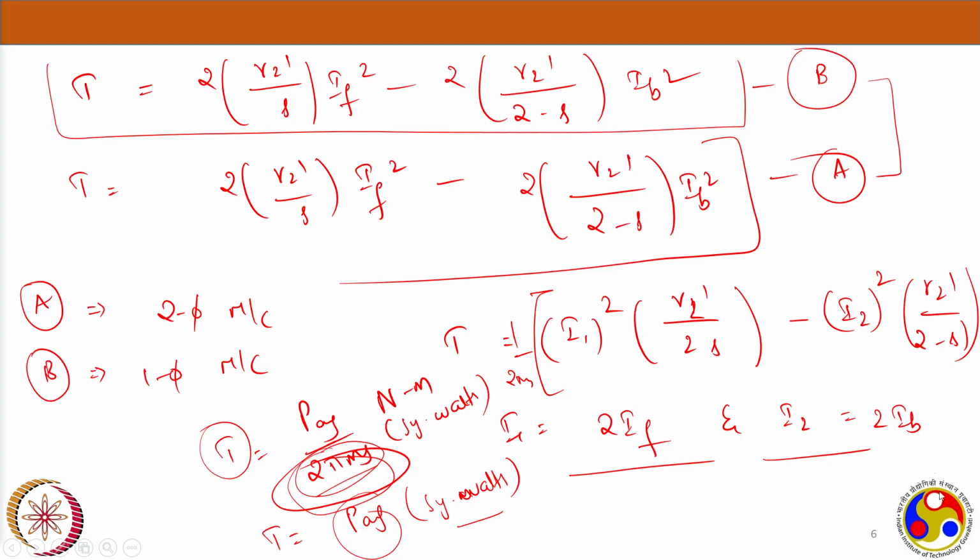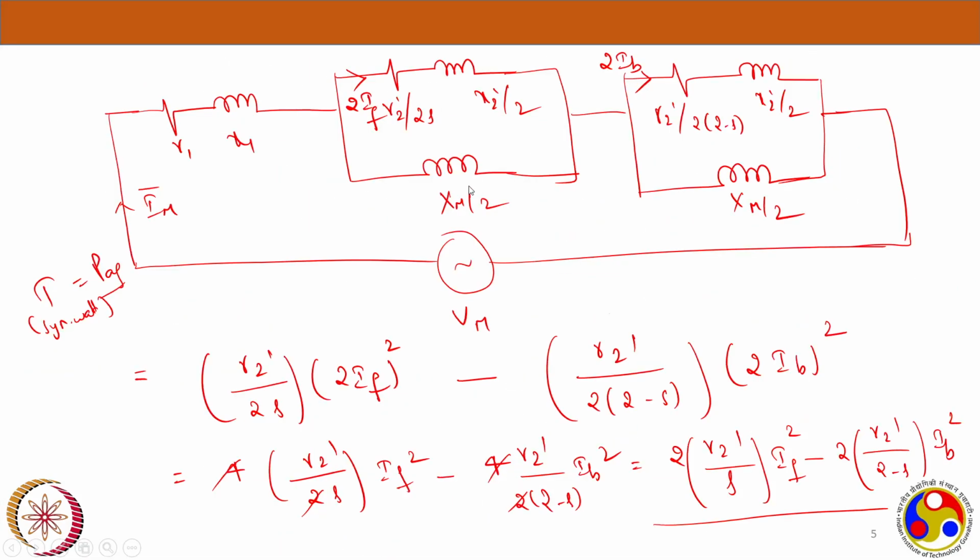So this RF, if you see this particular equivalent circuit, there is a parallel branch here. If you solve that parallel branch, you will get two resistances and reactances, RF, XF, and RB and XB, so that the equivalent circuit can look like that. To solve this equivalent circuit, usually people simplify those parallel branches. So here there is a parallel branch, RF, XF. Another parallel branch here, RB and XB.